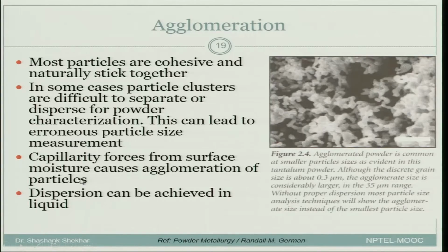Capillarity forces from surface moisture cause agglomeration of particles. So you can call it capillarity forces, or the reduction in the surface energy term, which leads to this reduction in the surface energy. Dispersion can be achieved in liquid. So if, let us say, you have obtained an agglomerated particle, one of the best ways to disperse them is to put it in a liquid.